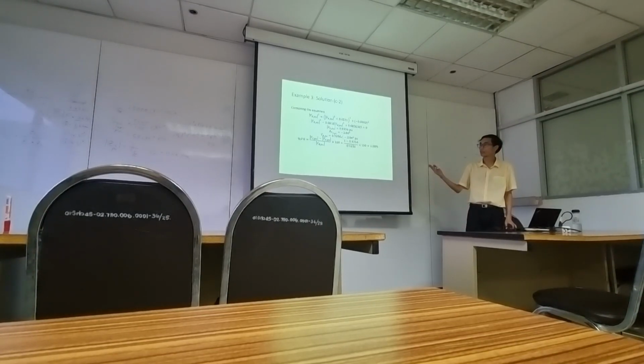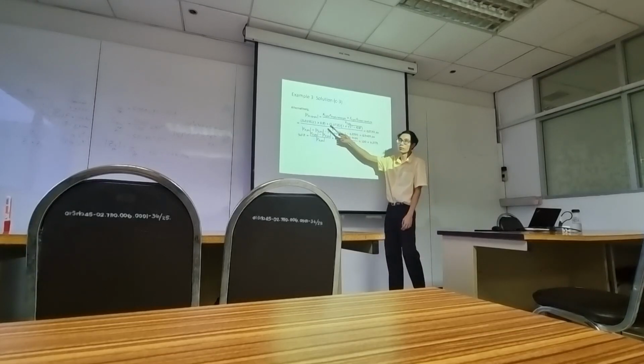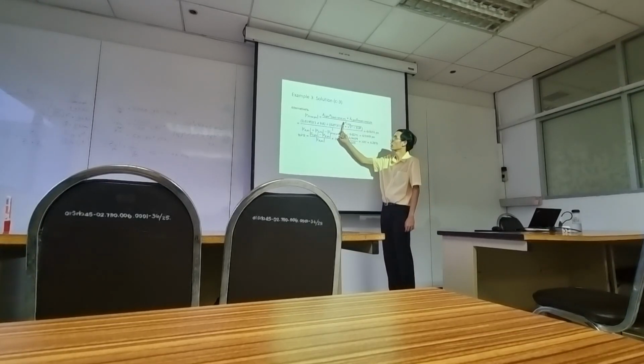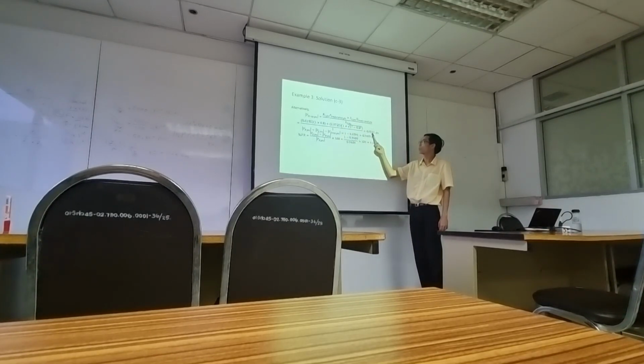Then if you think that this method is too complex, there is still an approximation method. We have already talked about this, right? Approximate the voltage drop by P plus XQ divided by voltage. This is P and XQ divided by 1. The voltage drop would be 0.0591. Calculate the load voltage, you get this, and this is voltage regulation.